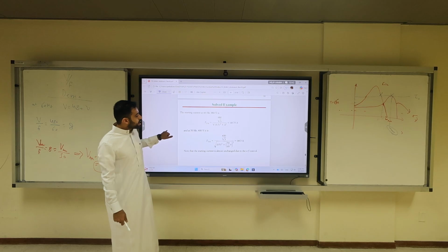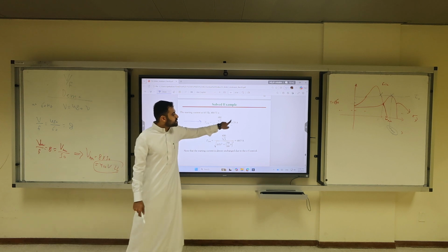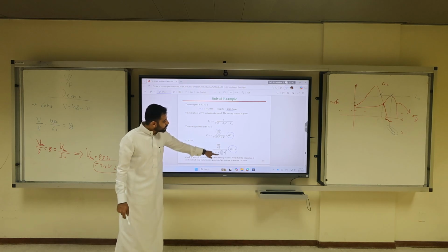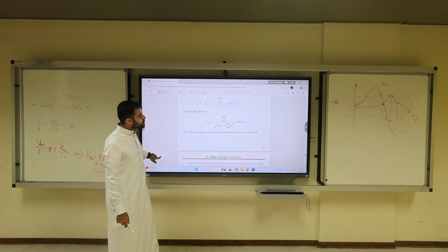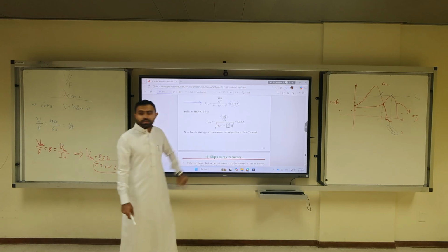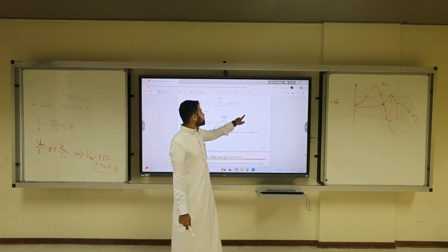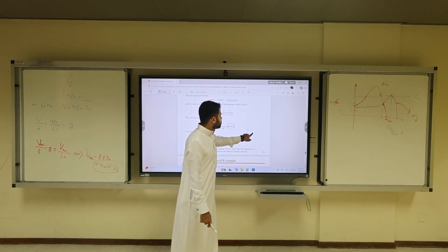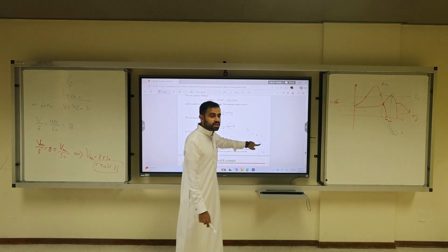And you do the calculation again with the starting torque at 60 hertz. With the old V over F, it was 68.75. You do the same calculation here. Keep in mind, he multiplied by 50 over 60. This is the frequency adjustment for X equivalent. If you do the same calculation here, the only change he made is the 480 becomes 400. So it will be 68.5. A smart student would use the old current, which is 82.21. He would just multiply it by 400 and divide by 480. That's a quick way to do it.